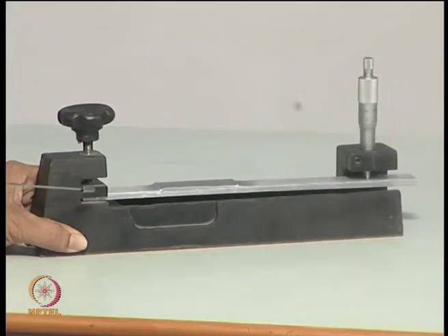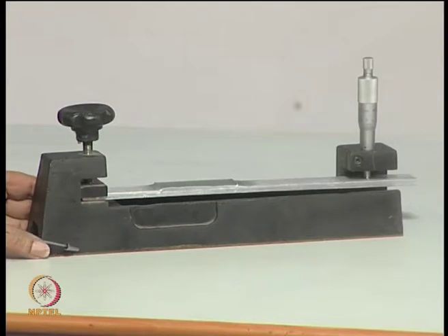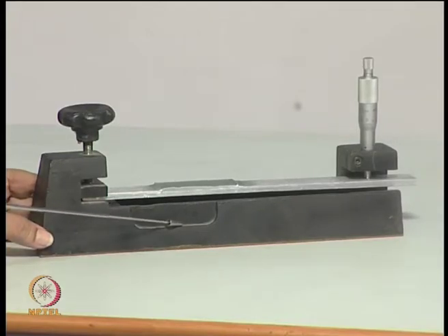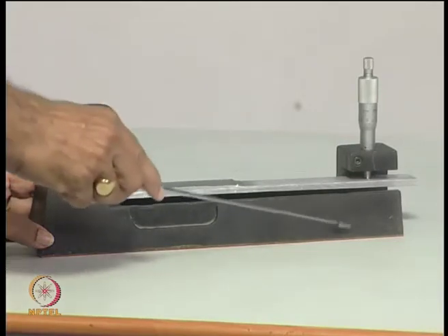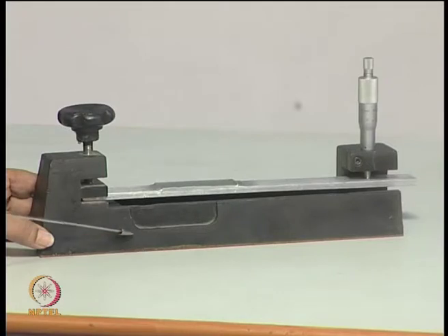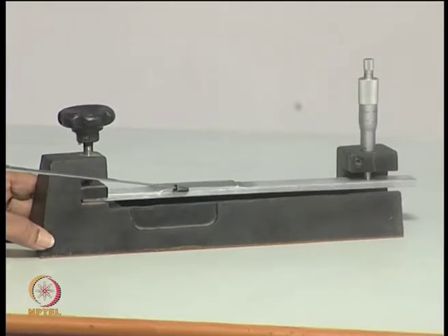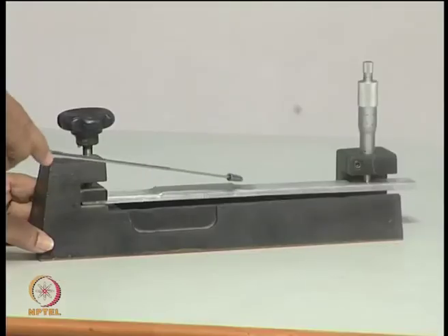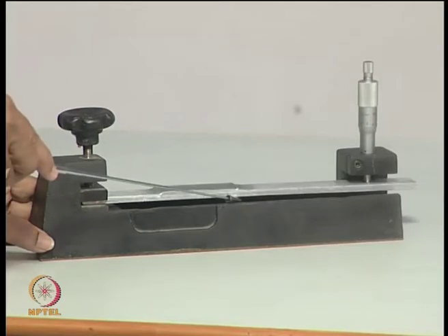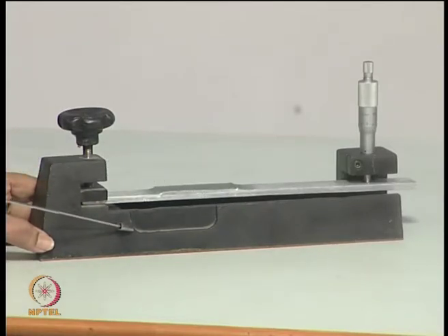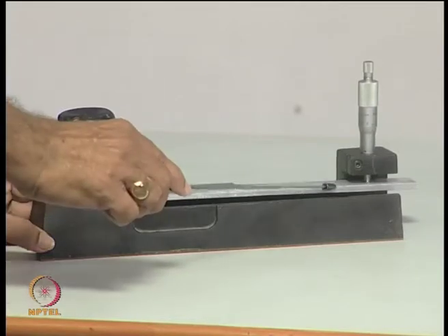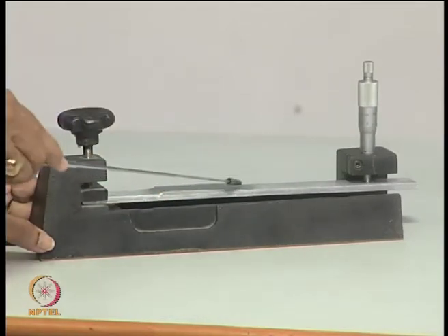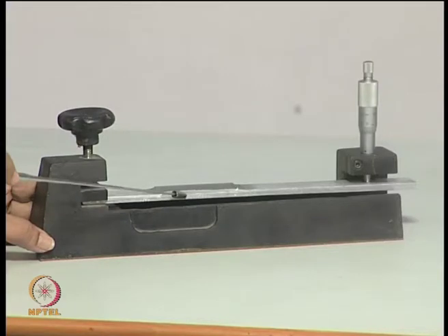The whole apparatus is very compact, and that is the greatest advantage, and all the coating techniques like brittle coating or strain gauges use only a cantilever for the measurement of pertinent parameters. In this case, we want to use this to find out the strain coefficient K, and the advantage is you use only a small amount of coating material to save the precious coating material. You do not need to apply it over the entire cantilever beam; you apply it only in the region where you want sufficient stress to reveal the fringe pattern.